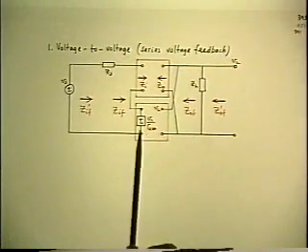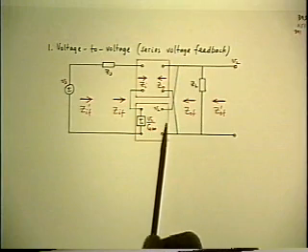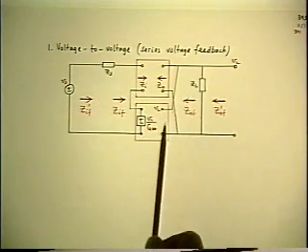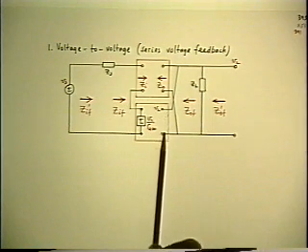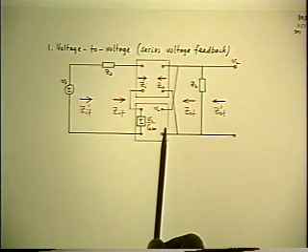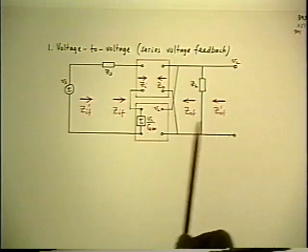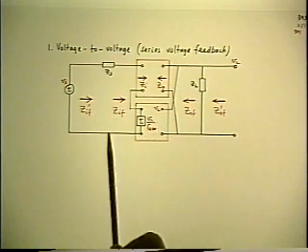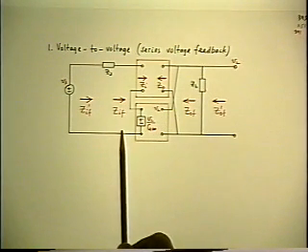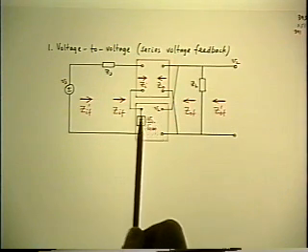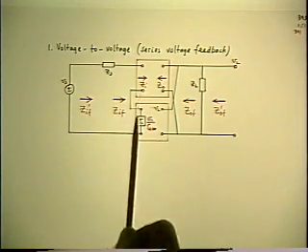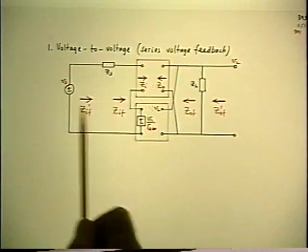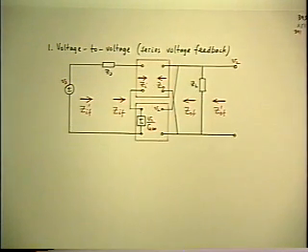So there's the same thing with the connection made. You connect the feedback box in parallel with the output, which you usually describe as sensing the output voltage. What you're really doing is choosing the output voltage to be the signal that is fed back. And then the feedback path converts it to a different voltage, which is then connected in series opposition in order to do the differencing.